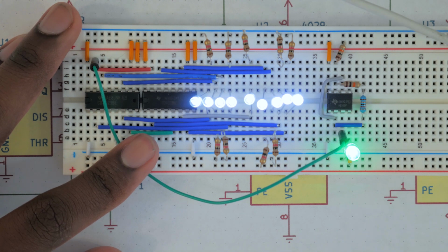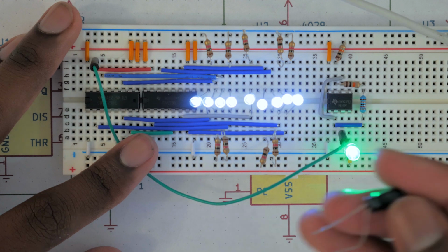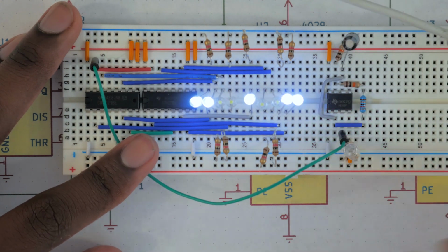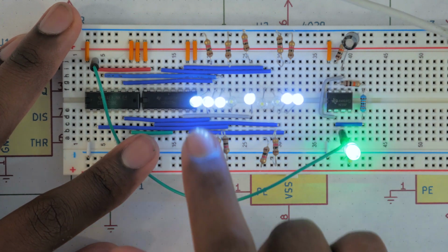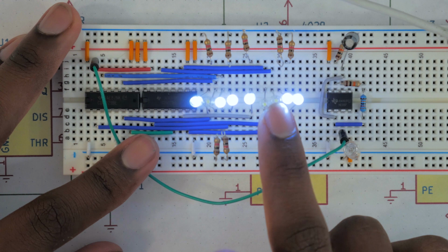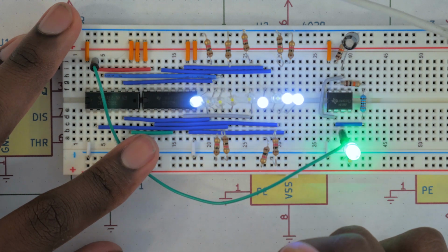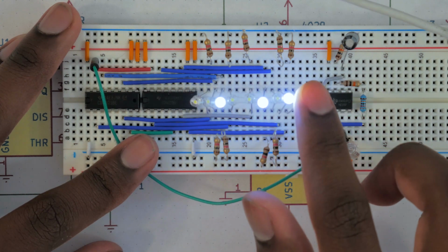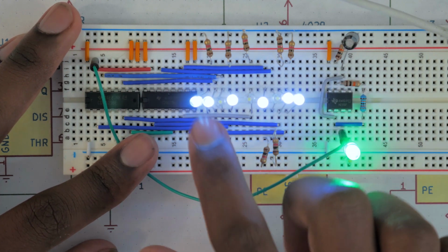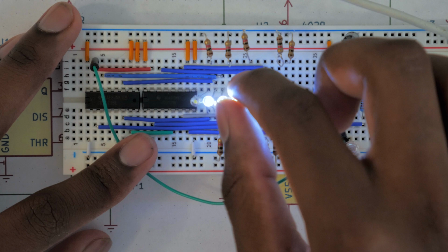So I'm going to change out this 47 microfarad for a 4.7 microfarad, and that'll give us considerably faster. So now we can take a look, and you can see that we are actually counting through the values just like we were seeing earlier. Right. Now this being high actually means that it's a 0, remember that. But beyond that, just look at this beginning portion, it's counting just fine.